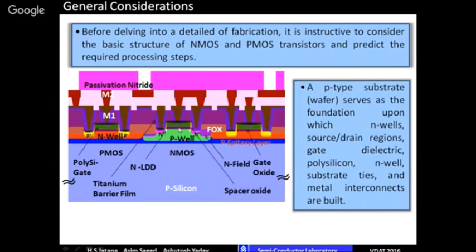This thing is a gate. This color is gate oxide. This is poly, this yellowish one. This is poly. This is the contact. Brown is the contact. Again, this is a salicide. This is a via, so it's going on top. So this is one transistor. This is another transistor. This is Fox.